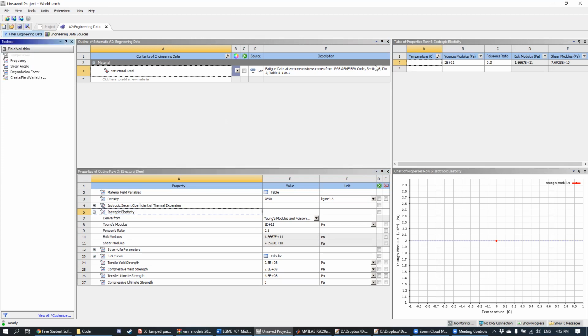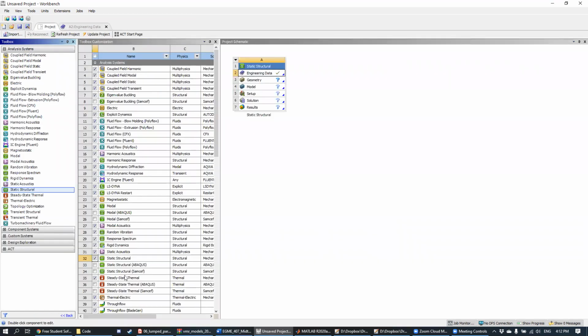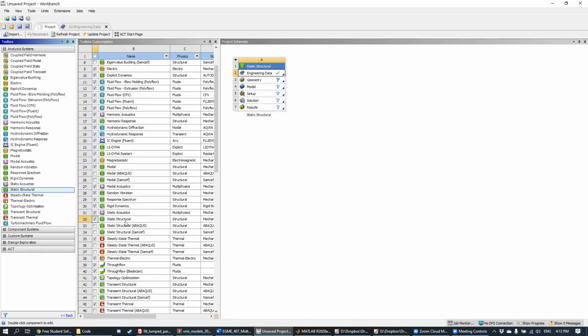Yes, sir. Oh yeah, what's up? If you go to the very bottom of ANSYS on the side, from where you pulled out static structural, it says view all on the very bottom. I think it might pop up there. We were looking at this earlier, but for some people, even when you enabled it, they said they still had issues with dragging it in.